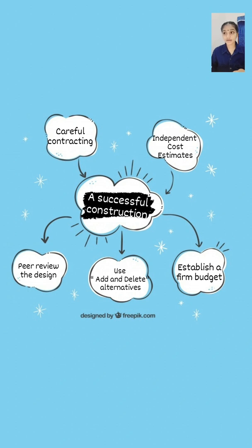Under this approach, the design team pre-plans certain components of the work which the owner may delete if the bids come in too high, and add if the bids are lower than expected. Making sketches of alternative design concepts helps communicate and fix the project scope of work, aids in determining project feasibility, and provides more input for developing realistic estimates, budgets, and schedules. Cost estimates are prepared for each alternative to ensure selection of the best system and components.